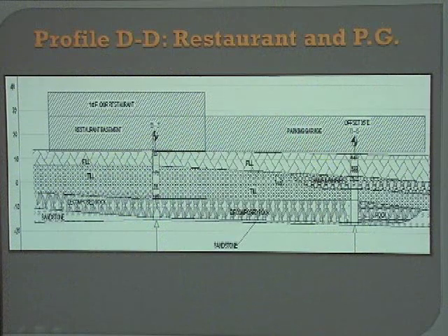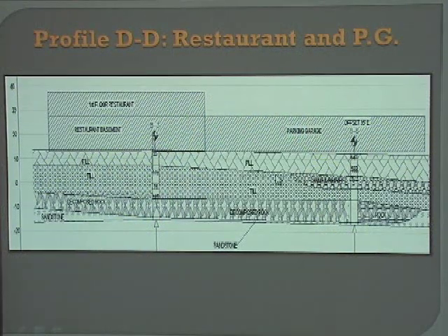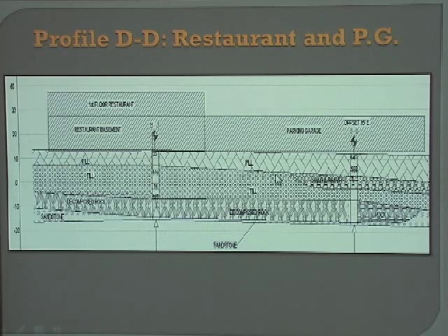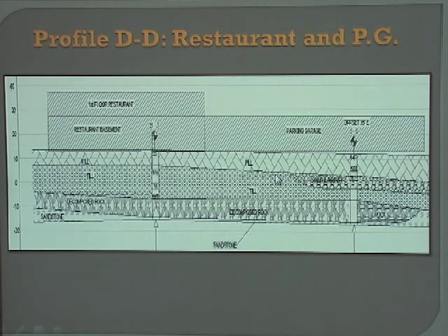We feel that the fill layer in this area is also sufficient to support our foundation for our parking garage, so we'll have shallow footings in this fill layer above our water table depth of 5 feet. Now Mohammed will talk about our bridge design.